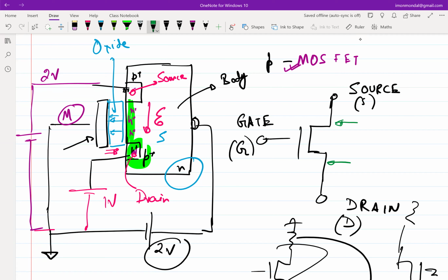And the moment you know which is the higher voltage terminal, you know that terminal must be sourcing the carriers, hence that will be the source. So in isolation, it is impossible to tell which side will be the source until you put a battery, until you define the quiescent voltages of the terminals. That is the peculiarity of a MOSFET that you should be mindful of.